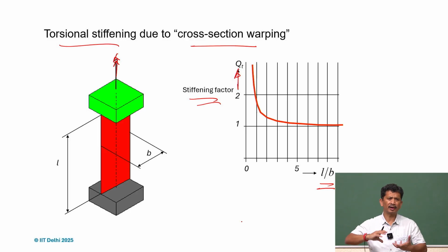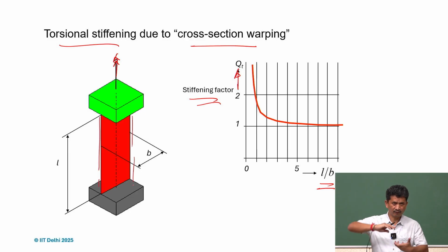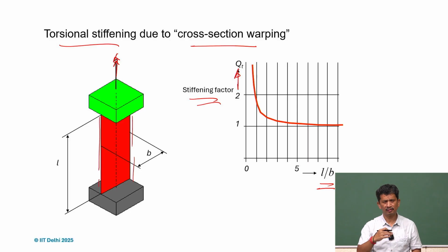And the reason being, as we twist, the outer members deform along the cylinder edge or on the surface. So it's more like a helix, but the center line is fixed. So initially all the lengths are the same, but as we are twisting, the lengths are changing.